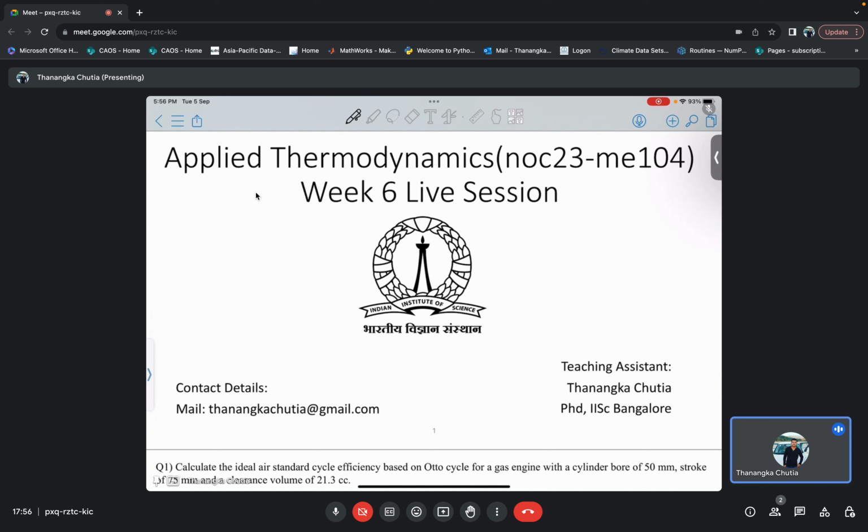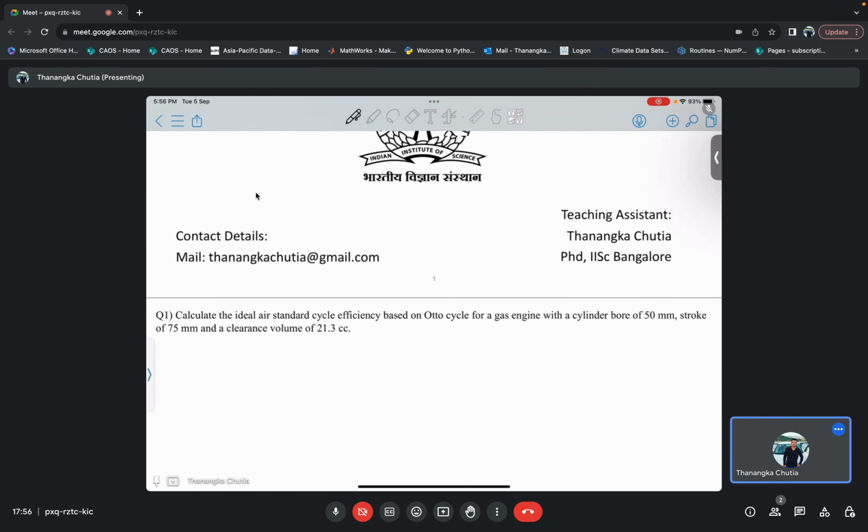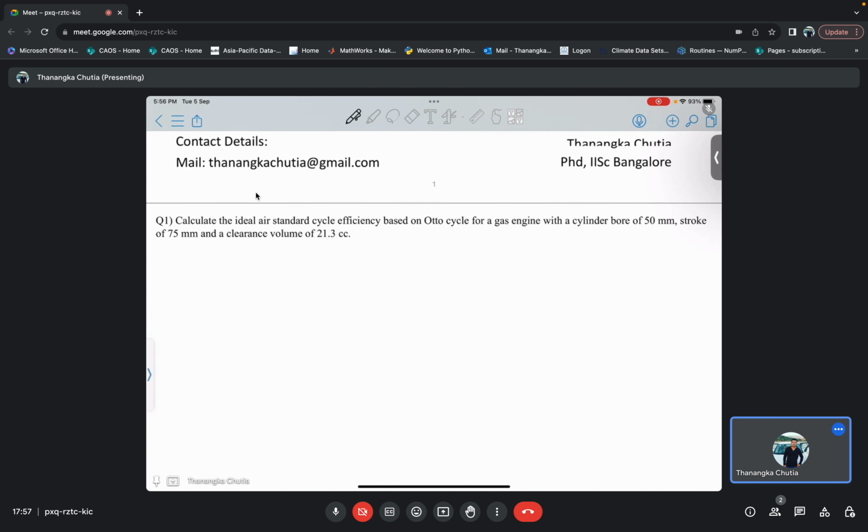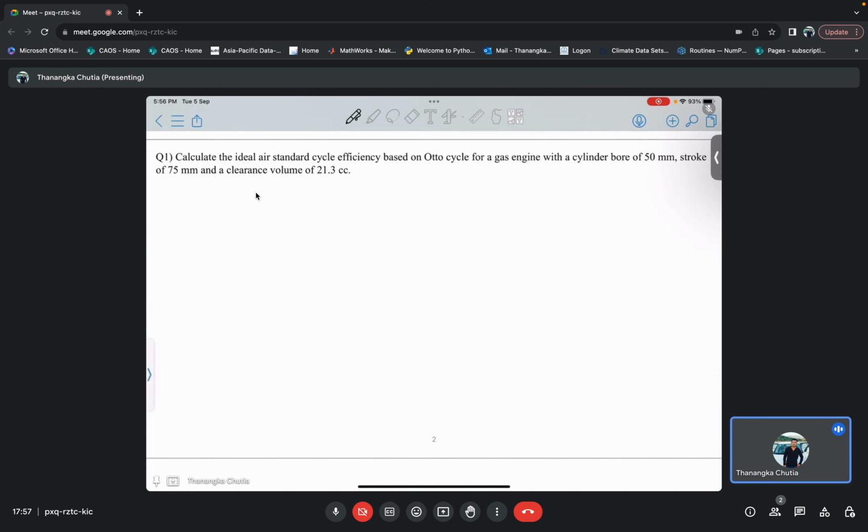Okay, so let us start today's class with the first question. It's given: calculate the ideal air standard cycle efficiency based on Otto cycle for a gas engine with a cylinder bore of 50 millimeter and a stroke of 75 millimeter and a clearance volume of 21.3 centimeter cube.